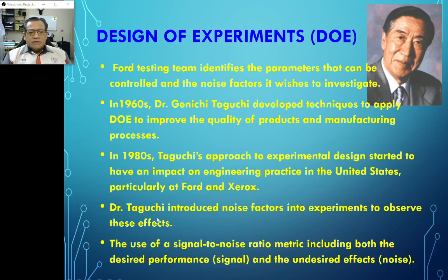So they decided to engage Dr. Taguchi's approach, which focuses on noise factors, and the experiment observes the performance and noise factor, which they call the signal to noise ratio. Signal means how clear your performance is, and how to minimize the variation or the noise of the performance.